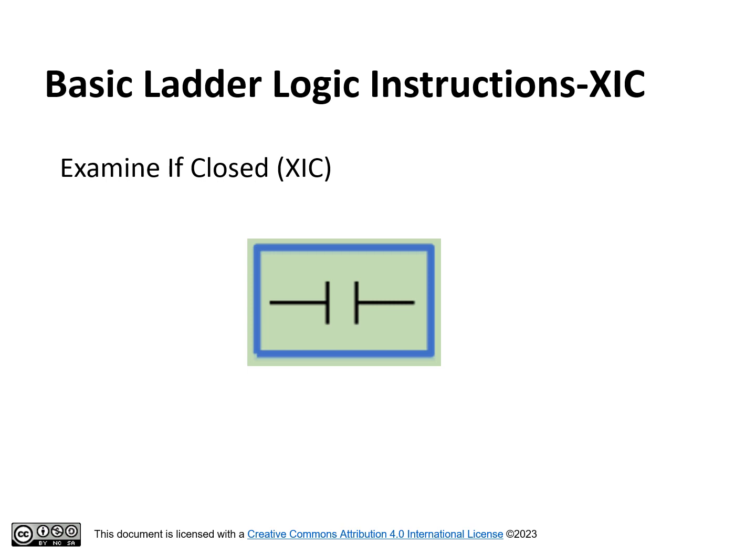This assumes that there are no intermediate instructions in between the input and the output instructions. If the corresponding memory bit is a 0 or off, this instruction will not allow continuity and therefore de-energize the corresponding output coil. Again, the same assumption that there are no intermediate instructions in between is made.